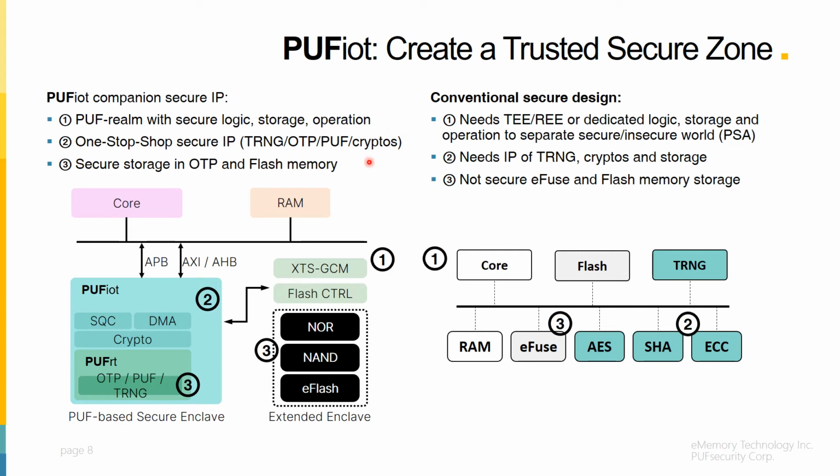Second, it's an integrated IP with all-in-one digital functions such as cryptographic engines and secure policy, and analog IPs of PUF, OTP, anti-tampers, and entropy source from jitter noises.